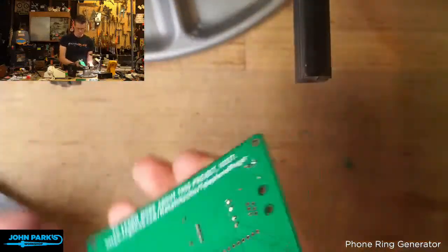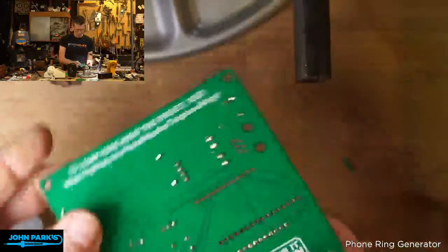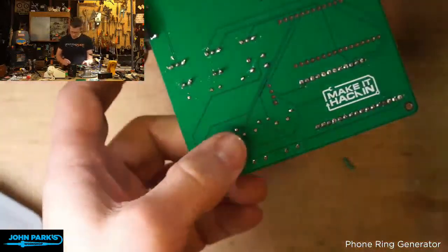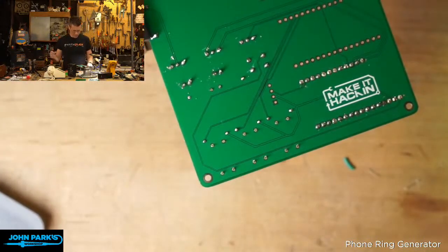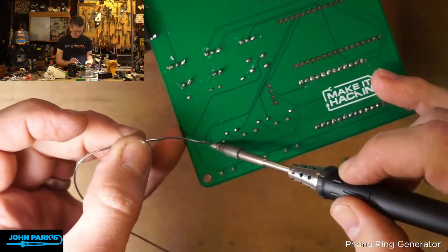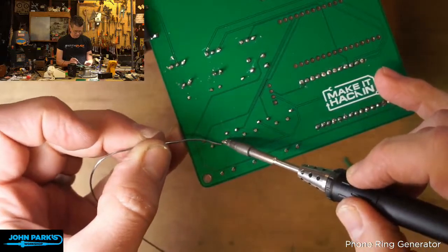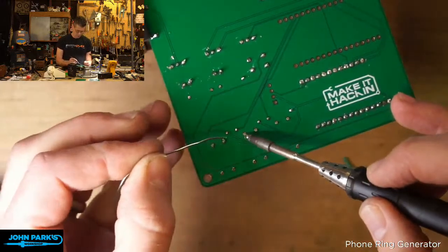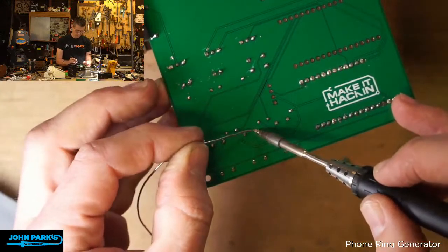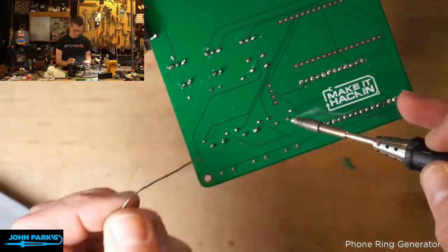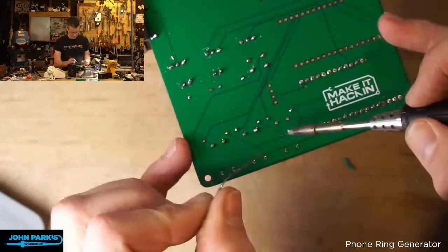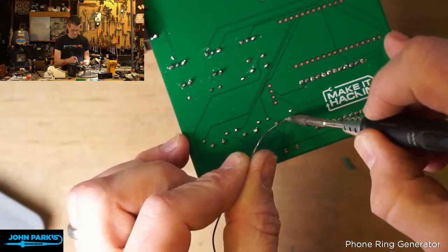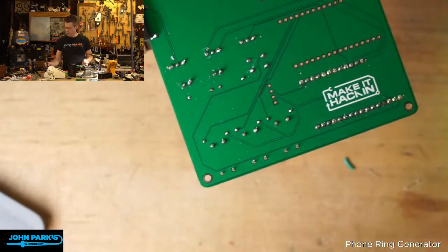And don't forget on parts like that to actually solder them. This is something I've done more than one time in life, where there's a part that goes in so solidly you then kind of forget it needs to get soldered, and it works intermittently. I've had that happen with IC sockets, which can lead to really weird results. Or push them into place, maybe solder the corner pins and then forget. There, you can tell I think I was on the ground plane there because that one took forever.